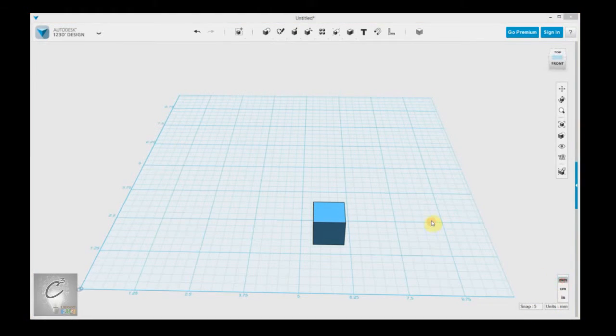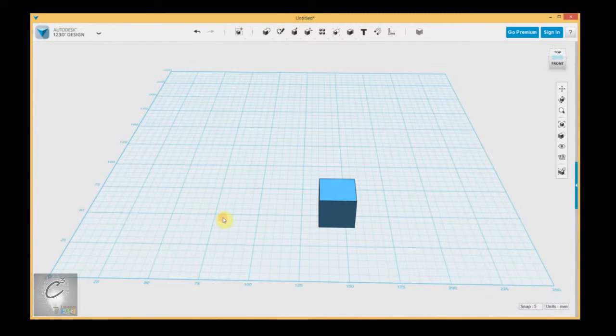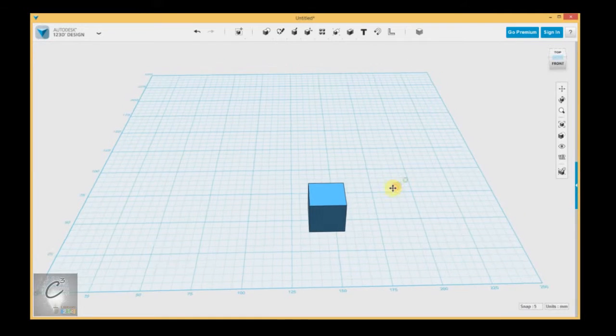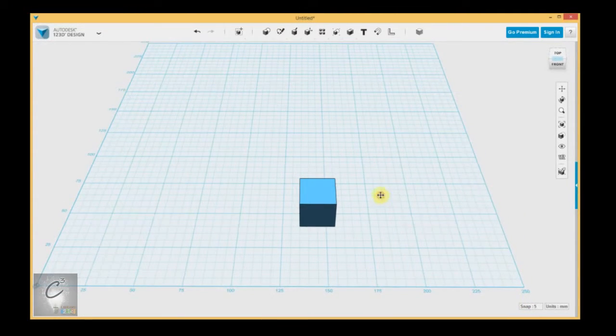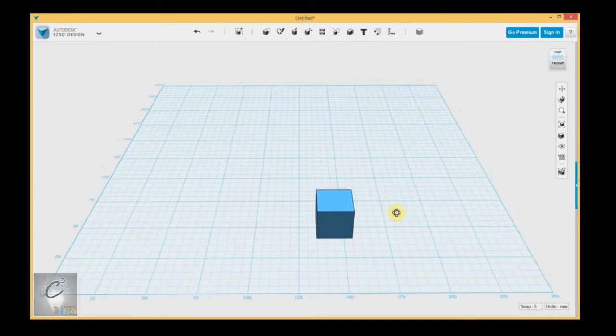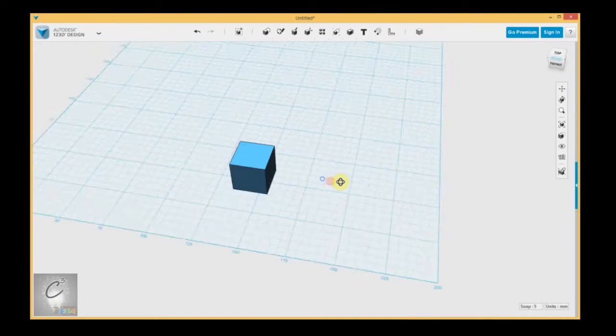Now, if you're a Pikes Peak Library District patron and you're doing this mostly to get some 3D prints going, I recommend you design in millimeters, or design in inches and then convert to millimeters at the end. The reason is that STL files save the numbers of the measurements that your object's dimensions are recorded in, but they don't actually save the unit.